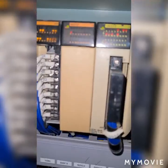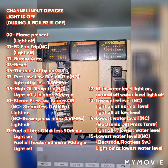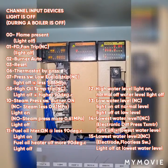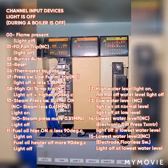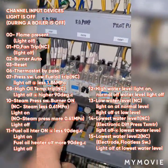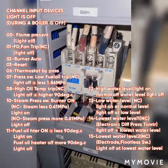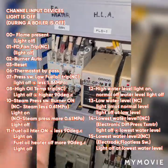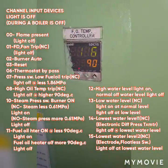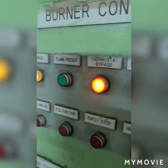And here, as you will see, the input channel 00 for flame present light is off, and the input channel 01 for forced draft fan trip is also light off. As you can see, now the forced draft fan, fuel oil pump, and pilot burner pump are all de-energized. This fuel heater relay is switching off and on while maintaining the temperature of the fuel.